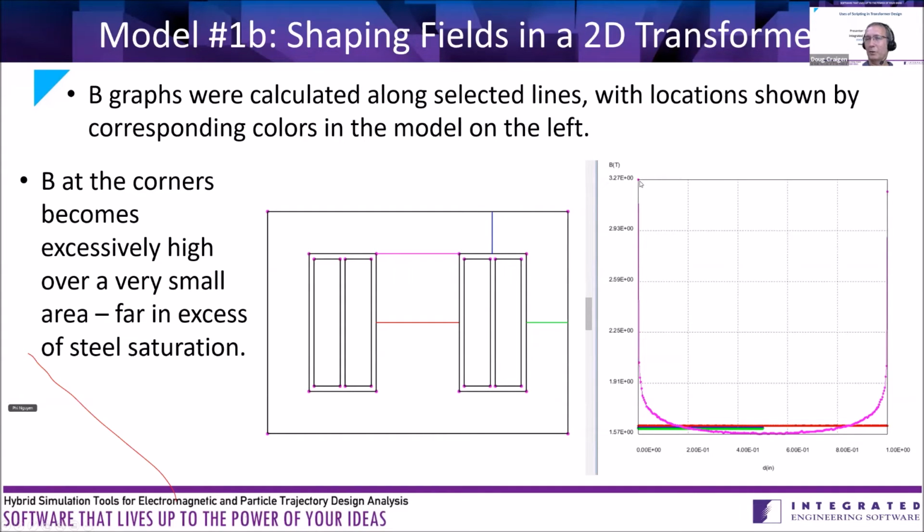And in fact, it probably won't go as high as 3.27 if I put in more time in the analysis and get the nonlinear characteristics correct. What I'll probably find is because the initial analysis says it's that high, what's actually happening is the flux is starting to cut the corner there. And again, if that's undesirable, it most likely is, then you want to work around that.